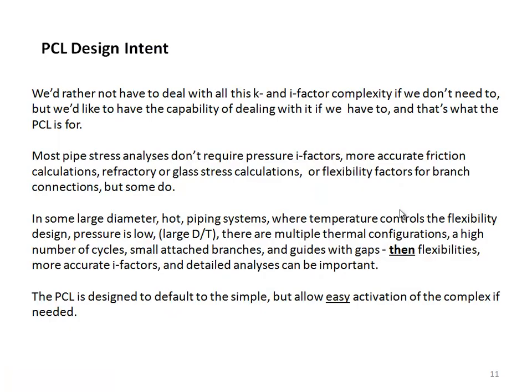We'd rather not have to deal with all this K and I factor complexity if we don't need to, but we would like to have the capability of dealing with it if we have to, and that's what the PCL is for. Most pipe stress analyses don't require pressure I factors, or more accurate friction calculations, or refractory or glass stress calculations, or flexibility factors for branch connections, but some do.